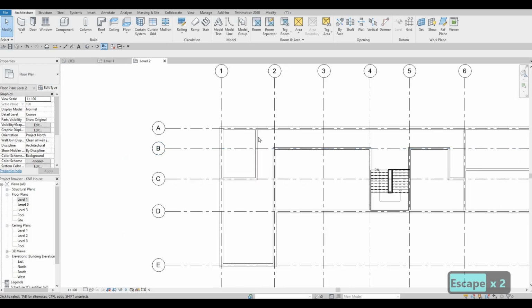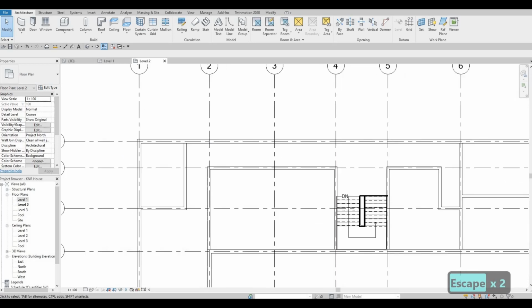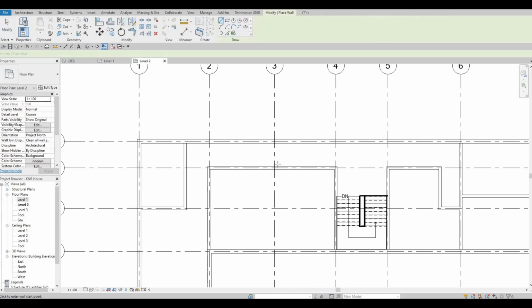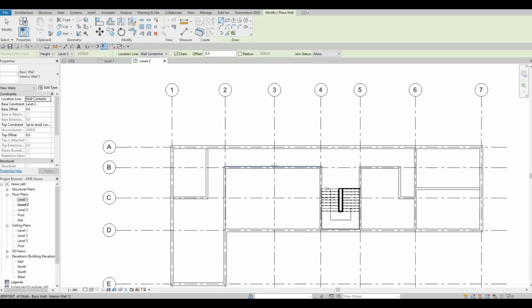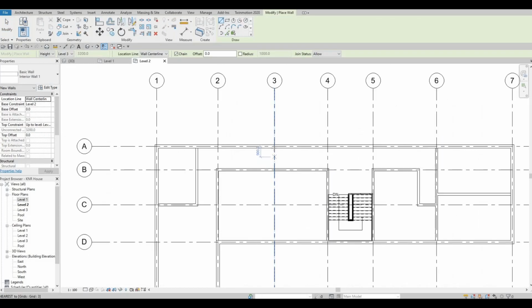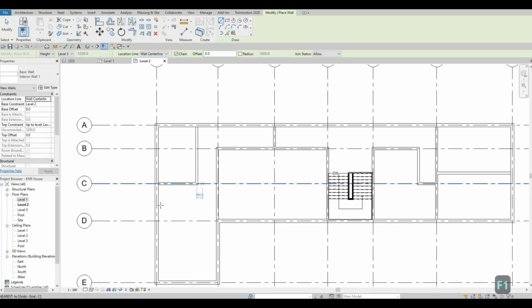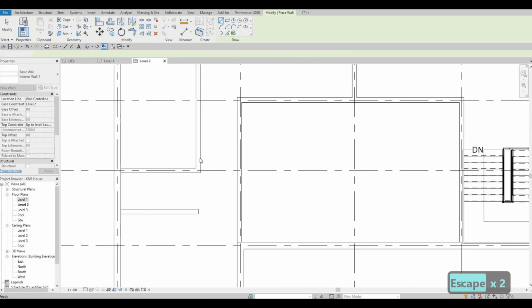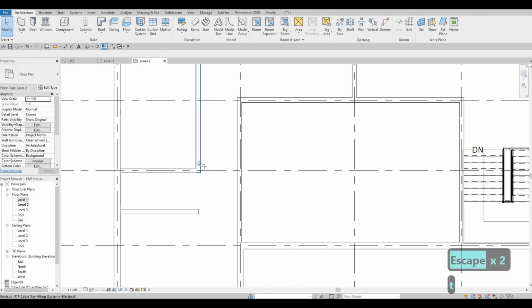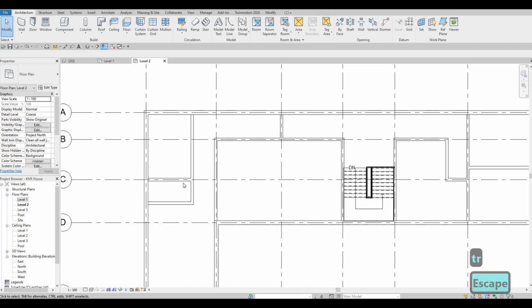and here this will be the ensuite. And then I'm going to add another wall on A3 to B3, like that. I'm also gonna add in a wall in between here, and I'm just gonna extend this by using TR, trim and extend this wall.